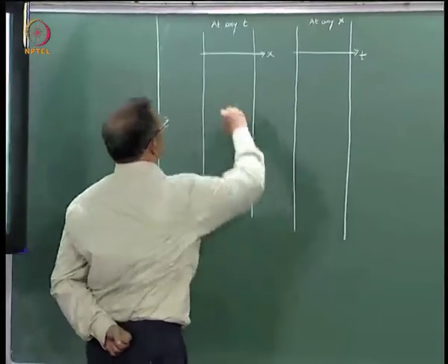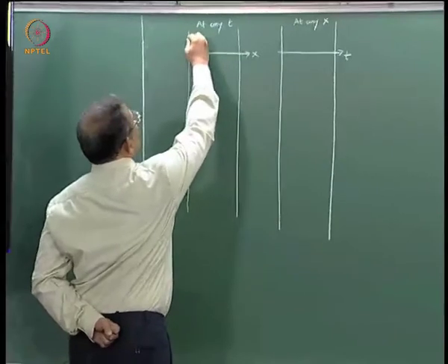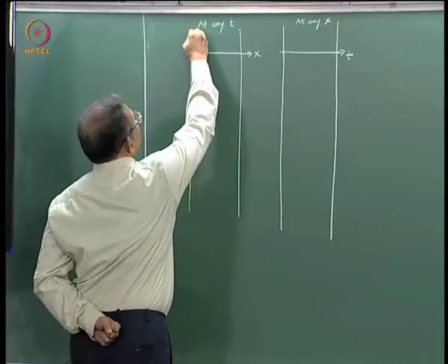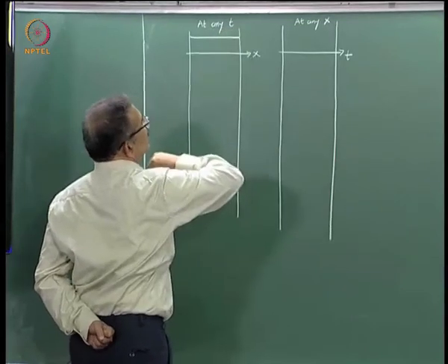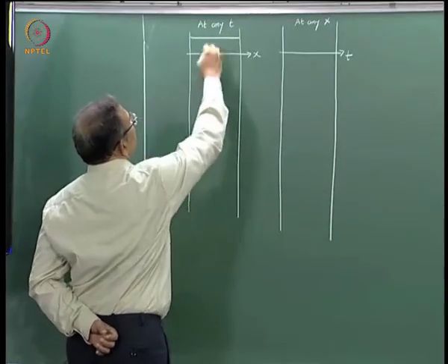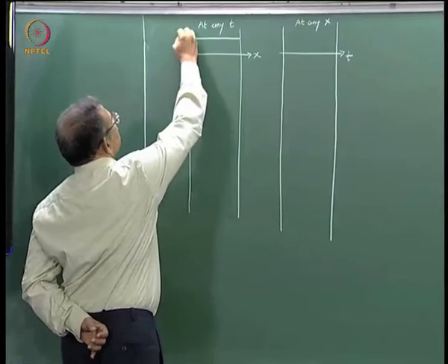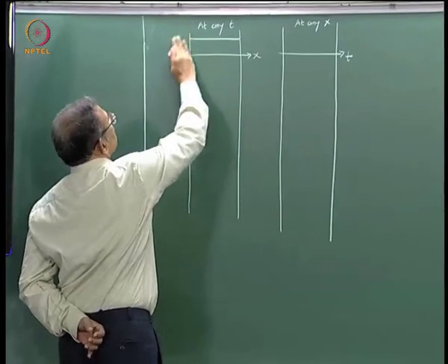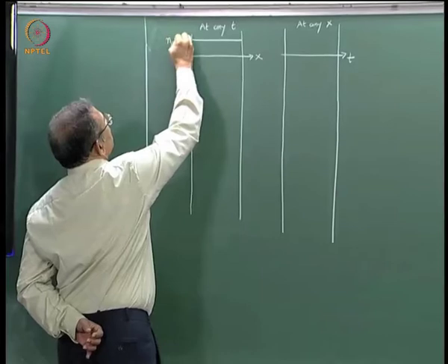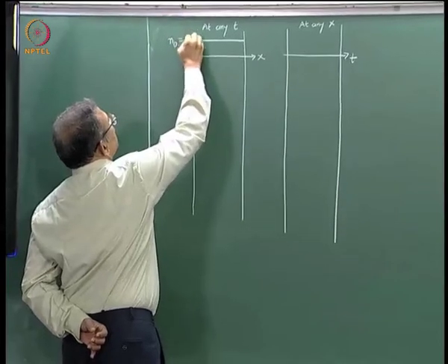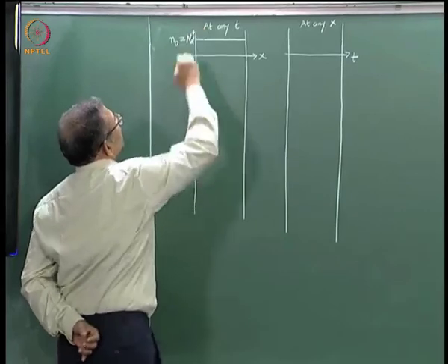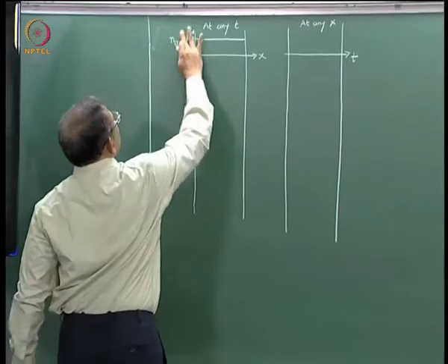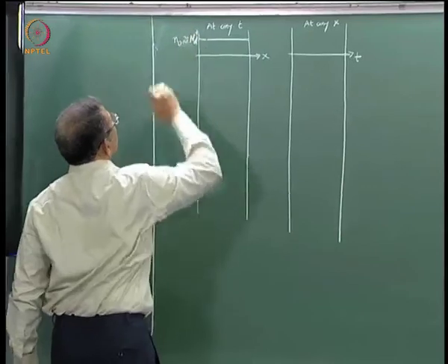Now the first condition was that the semiconductor is uniform. This means, for example, that the doping level is the same throughout the device volume. So this is shown here. I can say that N naught is approximately Nd plus, because we can neglect the contribution of minority carriers here.